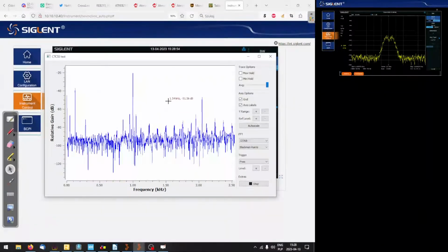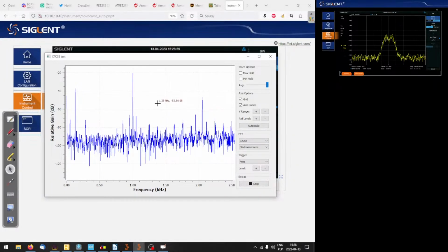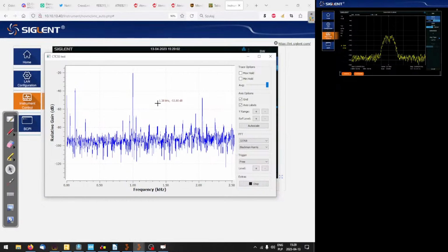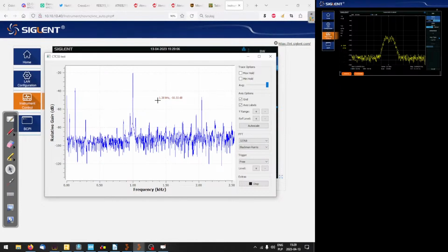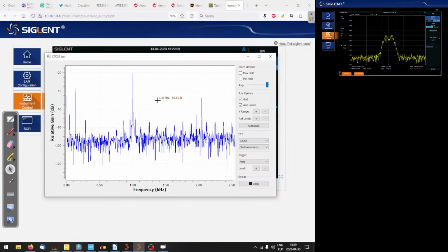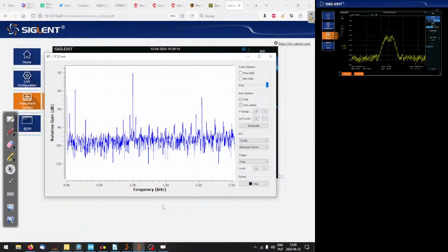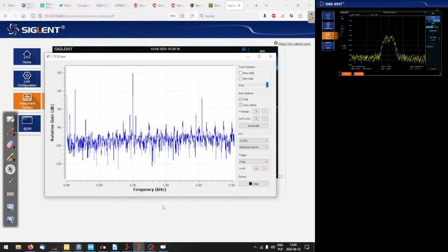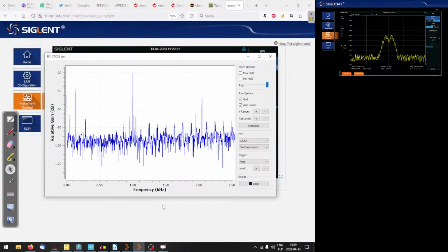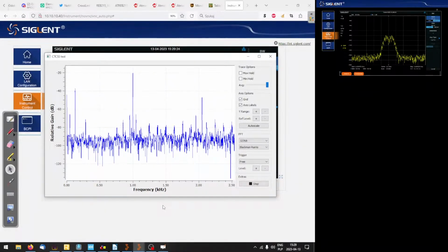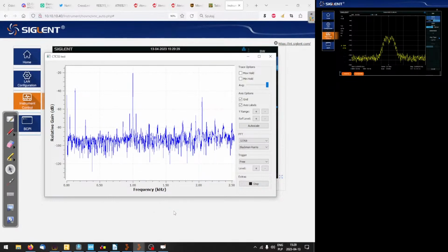Unfortunately, I don't have a radio that supports analog FM on 2.4 gigahertz. But there is something I can probably do. I can take my Baofeng and tune it to something in the 70 centimeter band, and then we can tune the 8086 to something in that region. So we can actually see if the 1 kilohertz tone gets through and is audible in the handheld. So actually, let's do that.